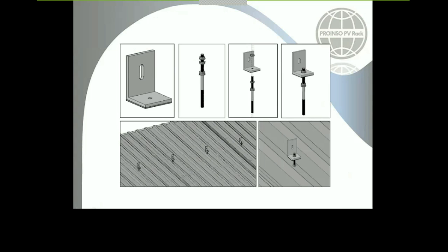For this type of kits, you have to go to the top of the roof and, first of all, do the setting out of the points that you are going to have inside your installation, and they have to follow a line with the purlins of the building, okay? Ensure when you do the setting out, without drilling anything, that they are aligned.